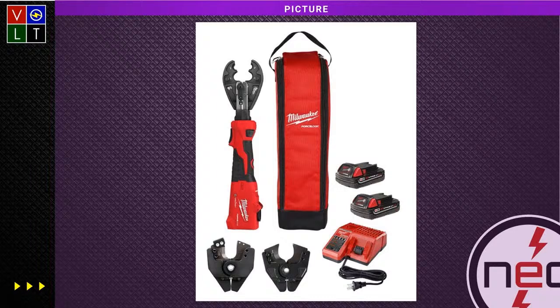They actually have a die imprint that goes into whatever crimp lug or crimp sleeve you use, and it tells you what gauge is supposed to be crimped on it. So the inspector goes over there, looks at it, and sees that you got number 8 crimped onto a number 6 or whatever. I don't remember exactly the scenario, but we got called out. We had to go back and fix it. And so that was something I learned.